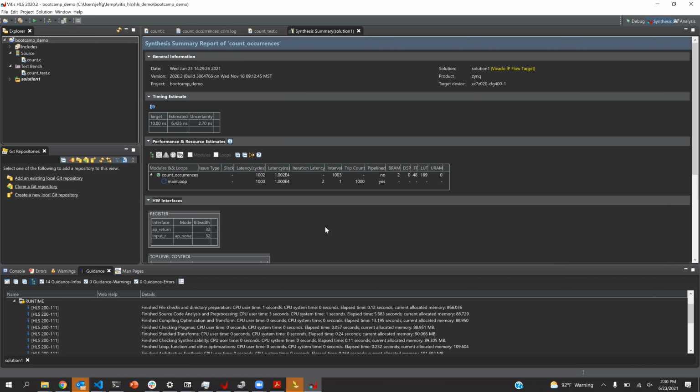At this point, it could create a net list essentially. But still, why might you not know how fast your net list is going to run targeting a part? Because you haven't run place and route on it. It hasn't actually decided where it's going to put it on the chip, so you don't know how far apart gates are going to be.